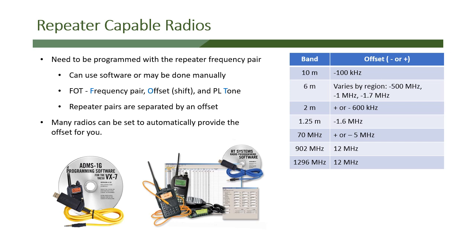But you can do this oftentimes with software. There is one software that's open source that's being worked for almost every popular radio these days, and that's Chirp. You can download Chirp, attach it to your radio, and then use it to program your radio in mass through a spreadsheet. And then you can save different configurations for the radio, different setups, so that, let's say you do